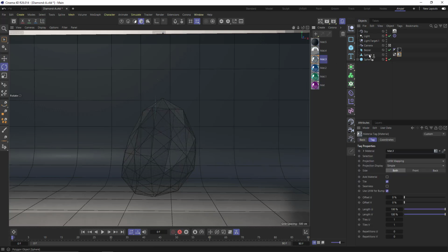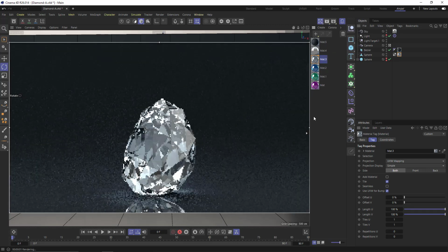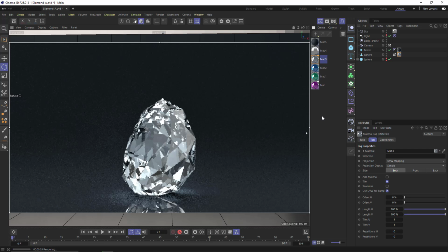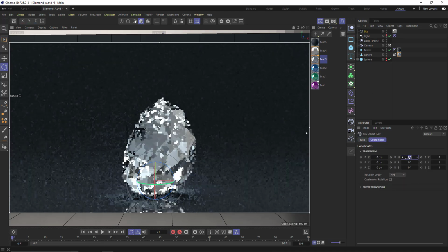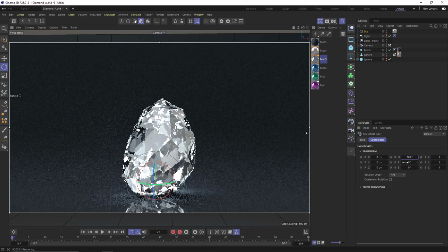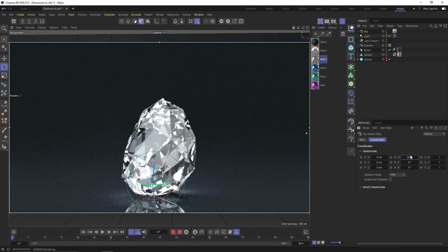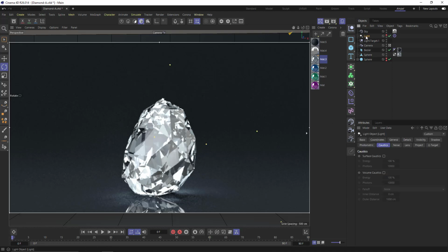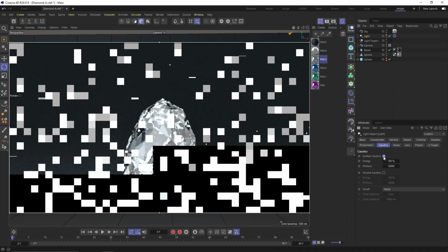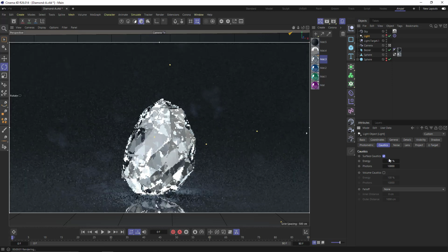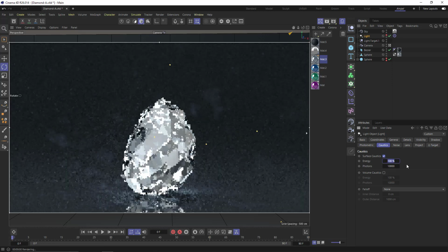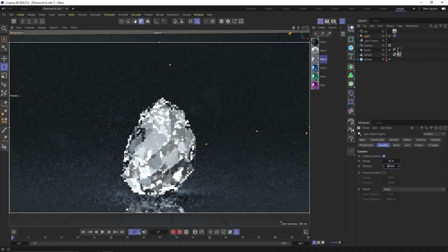We will start by previewing the render using the material. To do this, we will choose the interactive renderer, which gives fast results that are very close to the real render. Sometimes we need to change the direction of the HDRI to get the best reflection, and this depends on the type of HDRI. It is very important to activate the caustics option from the basic lighting of the scene so that the results appear clearly on the ground during rendering, as we see.